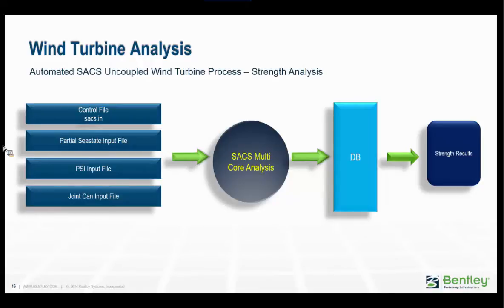In the previous fatigue analysis, I forgot to mention that you can also do a fatigue analysis of the pile foundation itself by generating a pile solution file. So for a strength analysis, we'll input all these files, we'll do a multi-core analysis, and then we'll pass the millions and millions of unity checks into a database. The database is then screened and filtered for the critical unity checks, and we'll supply information such as the load case in that particular simulation, which simulation, and which portion of the code has been exceeded.